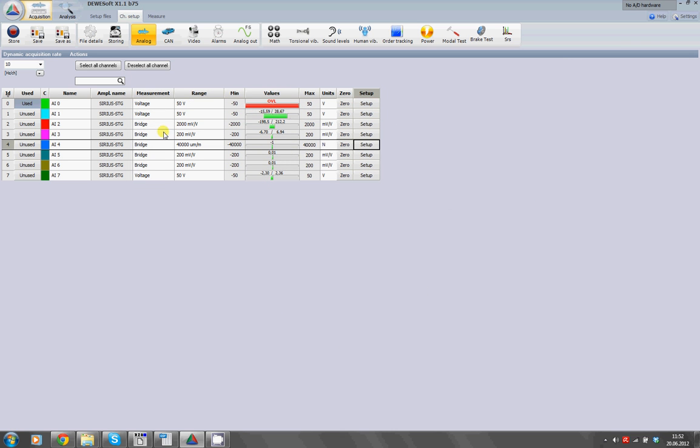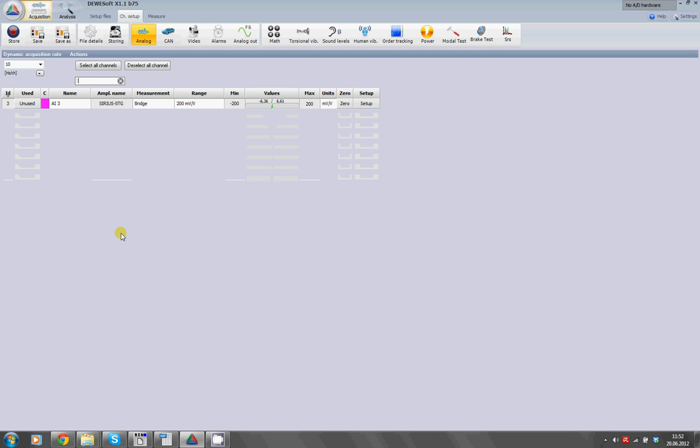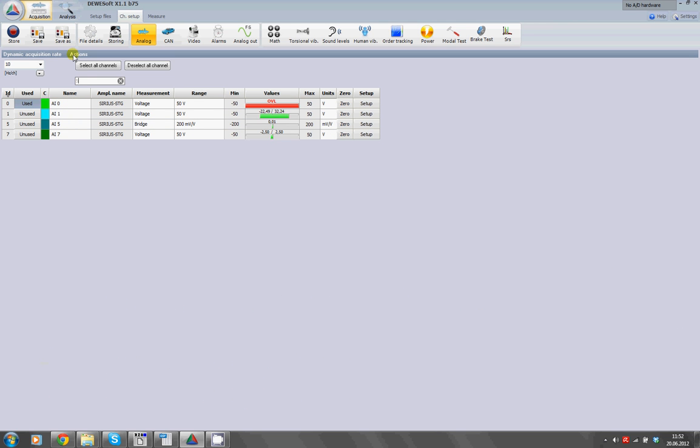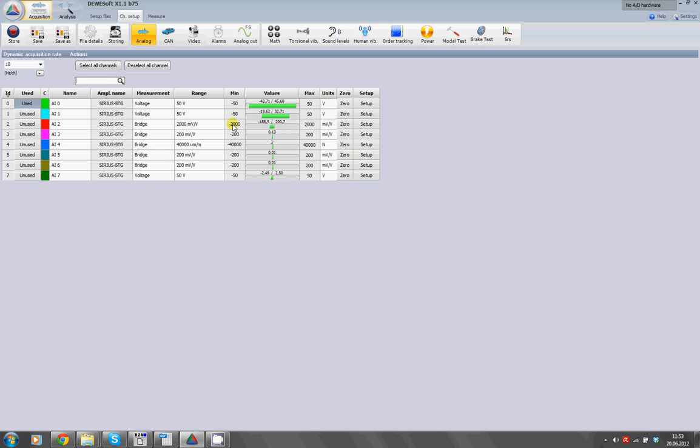Okay, there is one more thing which you asked for, the search function or the filter function. So now it's easily possible, for example, if I just enter a search criteria, that I get only the channels which are valid for this search criteria. This enables us, if we use the CAN bus, to easily find CAN bus channels which are active or just with a certain name.